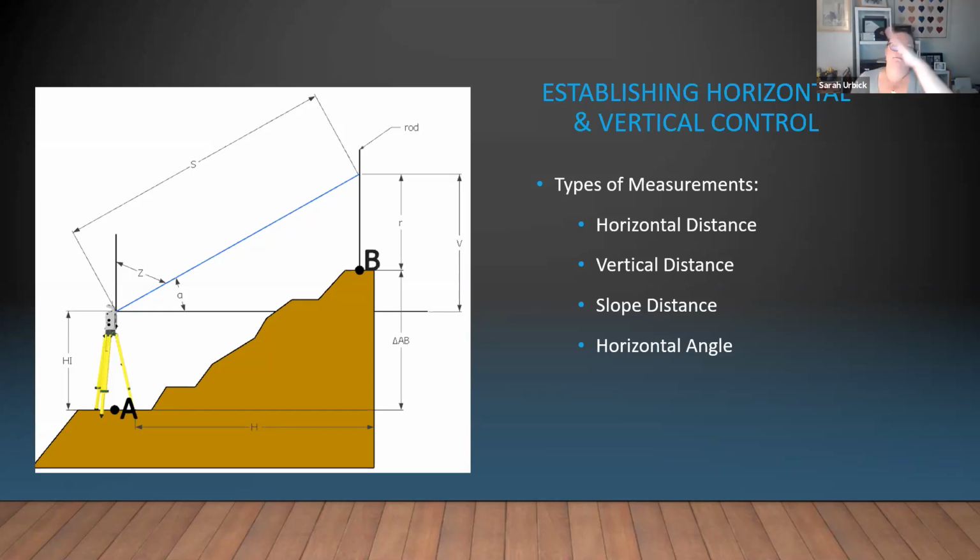Horizontal angle. That's going to help us find some of these other components. Do we know what that horizontal angle is? Some of the problems we went through last week, when we were doing the trig review. One of them was there's a radio tower on top of a building. We know how far we are from the building. We can measure what those angles are to the bottom of the tower and to the top of the tower. Using our trig lesson, we can find out that distance, that vertical component. What do we know? What do we need to find out? How do we get there?